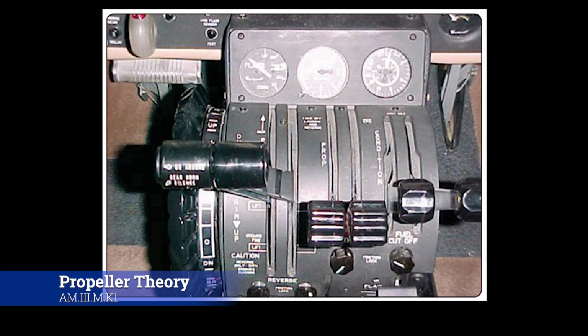Now, with a more complex aircraft, you have the ability to change the pitch of the blade angle on your prop, and that's done through the prop controls. That's always right there in the throttle quadrant, next to the throttle and the mixture.